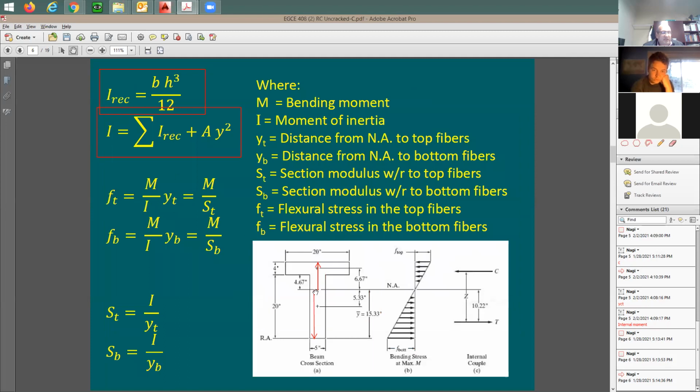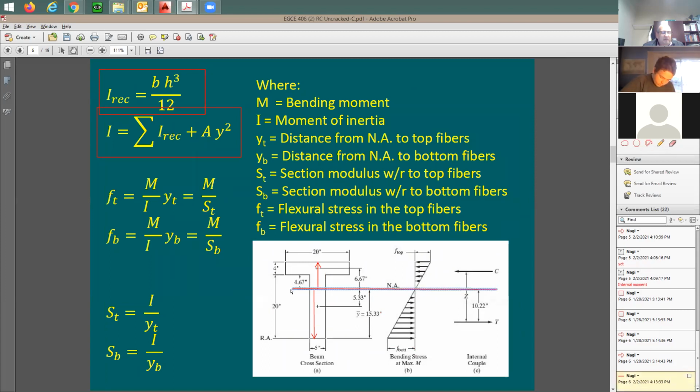For a T section, the centroid is going to be here. So we'll look now at the new neutral axis location, right? It's going to be shifted a little bit above the center or the mid height of the beam. So let's say if this is 24 inches, I'm expecting the center of the beam to be at maybe 12 inches from here. Look what happened.